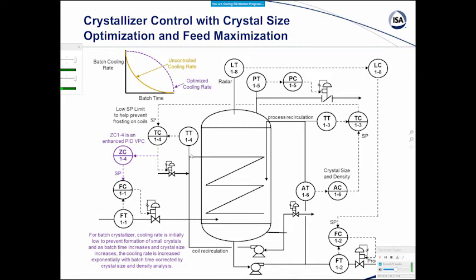Then it's going to cause crystals to form on the coolant surfaces, and then you get all kinds of problems. They're tiny, they're not the right size, and they start to coat the surface. All kinds of problems start to occur. So you have set point limits and restrictions on the inlet temperature of the coil here, and those little crystals forming and coating is called frosting.